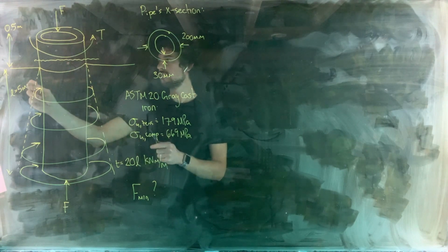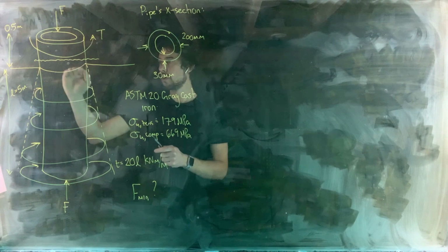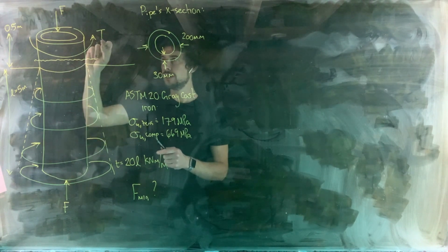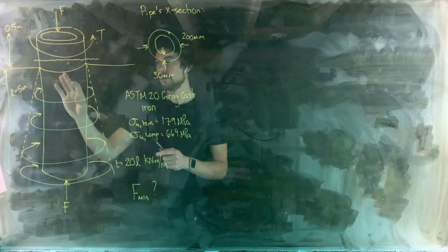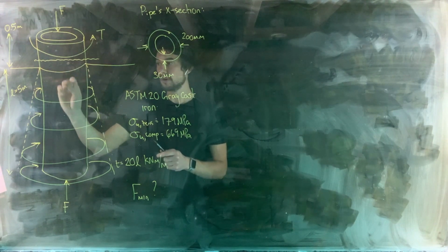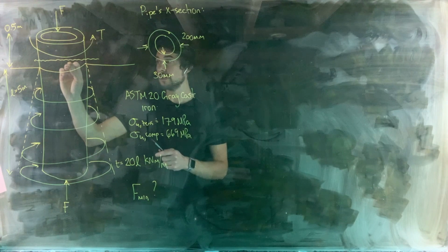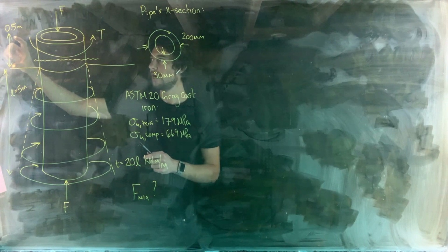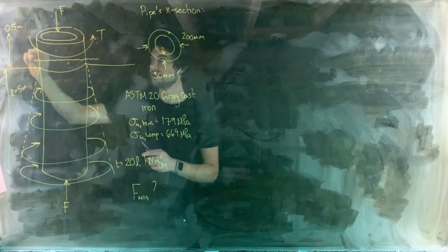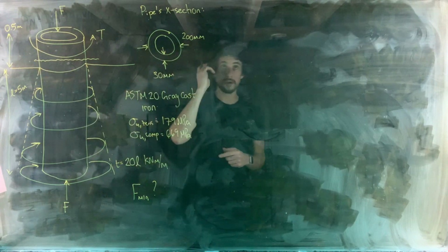Okay, as soon as we start section cutting lower beneath the soil, then we have some of the internal torque here being counterbalanced by some of the distributed torque. So the level of internal torque is going to start dropping as we move below the surface of the soil. So the greatest internal torque in the pipe will be in this 1.5 meter length that's above the ground. So let's do a section cut just somewhere through there.